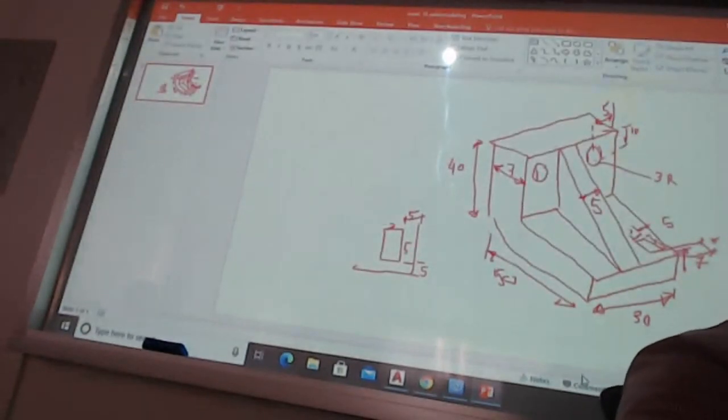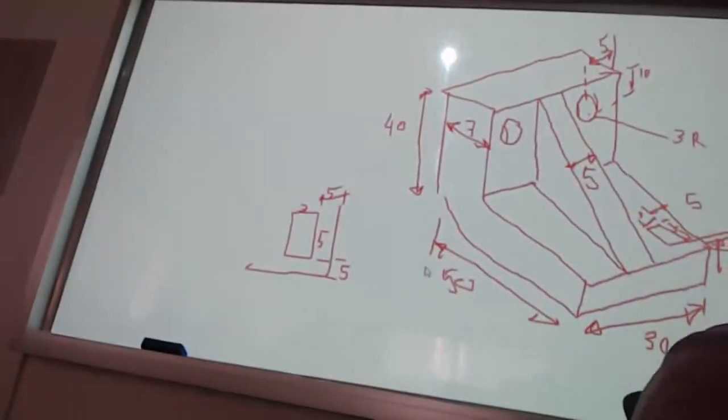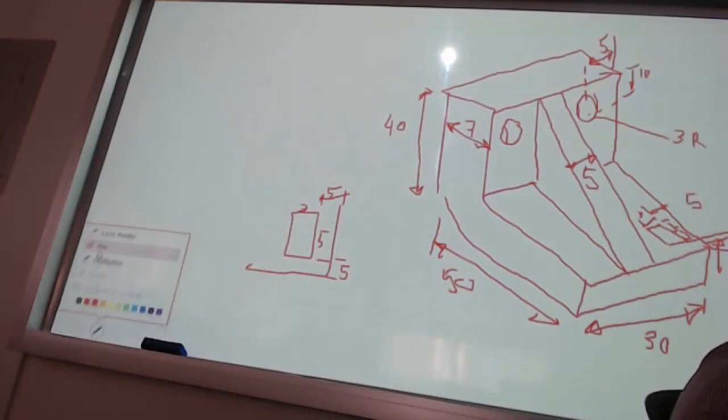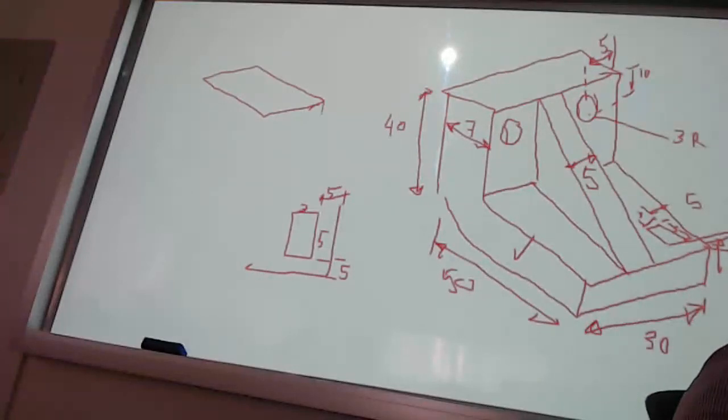Okay. And again, I'm gonna repeat the last 5 minutes, guys. As I said, how can I tackle this problem? There are very different ways to start the problem. As I said, maybe one of you will think this way. He will say it's okay. I'm gonna start by drawing the box which represents that base in the XY plane, and then extrude to come up with the lower part of the base, and then come to this one and draw a square or a rectangle, and then use press pull to create the whole of that base.